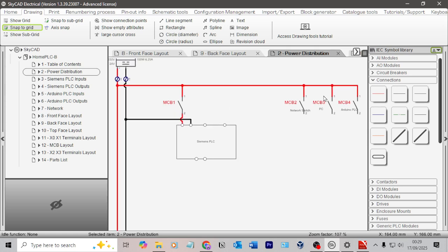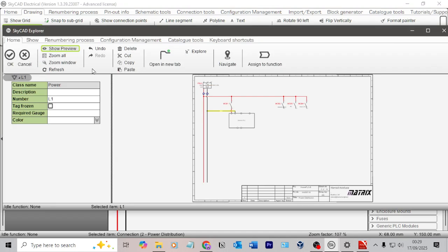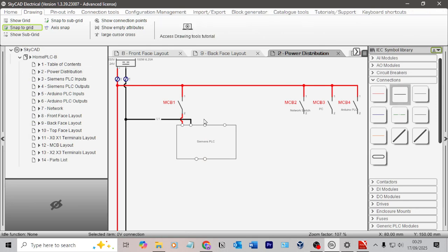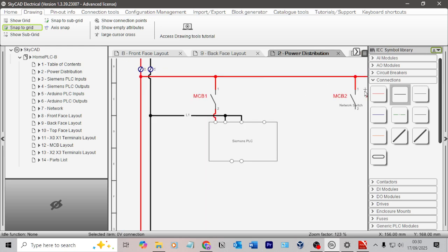So do I do it like that, or do I do it with the terminals drawn? I don't know. So this is also again another 0 volts, but again this looks like a double crimp, and it's not a double crimp. It should be a double crimp actually. So I think I'll just buy some double crimps and then make this a double crimp, and then that's actually legit, because those all should just be a double crimp. So I think I will just double crimp all of them, and that then solves the problem.